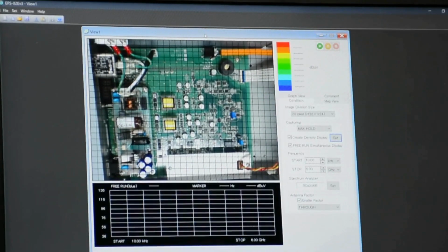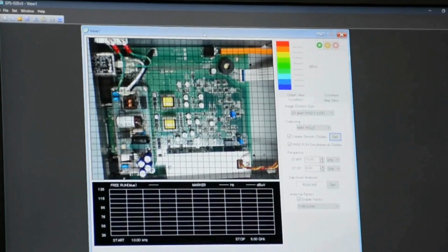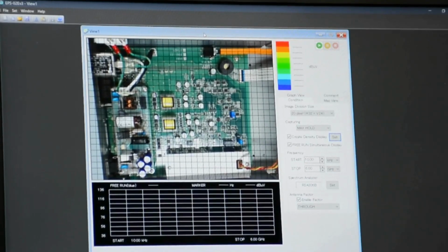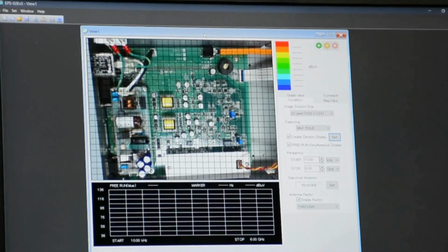Your room has to be bright enough for the camera to recognize the probe and see the EUT. If the USB camera is not connected, you cannot start a new measurement. As long as you have the web camera connected and the USB key connected, which is your license key, then you can start your measurement.